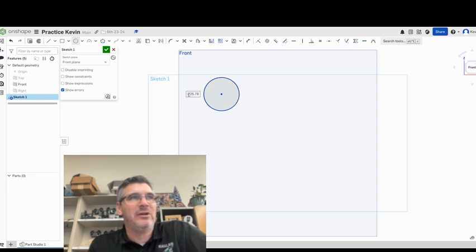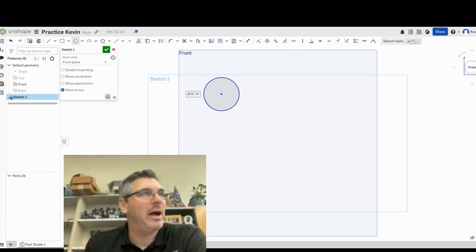Now this right here says that's the diameter symbol. The diameter is 26.78 millimeters. Now I want to make it 1 inch, and it will convert to millimeters for us. To do that, we have to dimension it. So step 2 is our dimension tool. So I go over here to the dimension tool. My mouse cursor's on it right now. And I selected it. It turned gray.